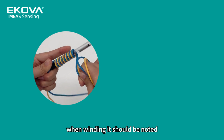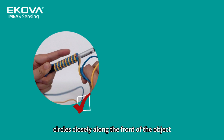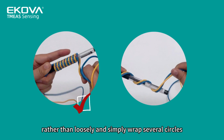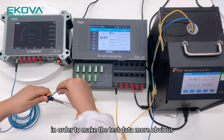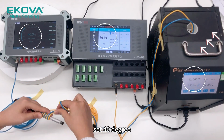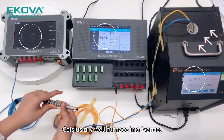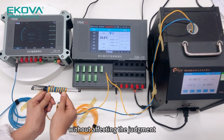When winding, it should be noted that you need to wrap several circles closely along the surface of the object, rather than loosely wrapping several circles, otherwise it will affect the test result. In order to make the test data more obvious, I have already placed both types of sensor probes into a dry well furnace set to 40 degrees Celsius in advance. If there is none, they can be placed directly in the air without affecting the judgment.